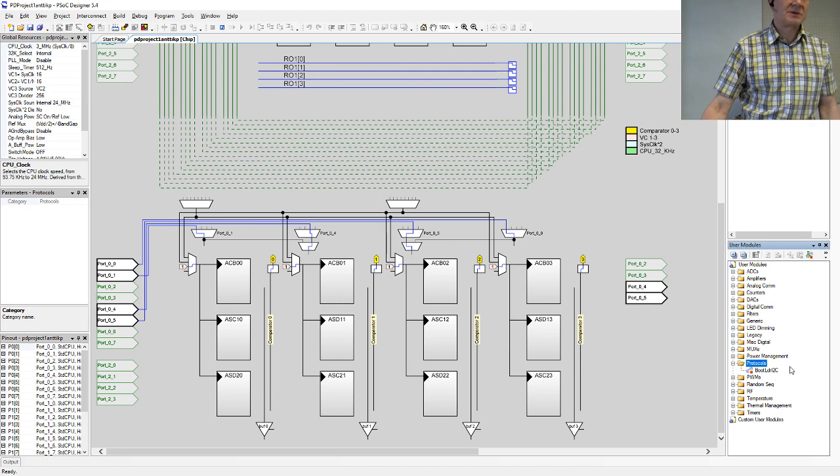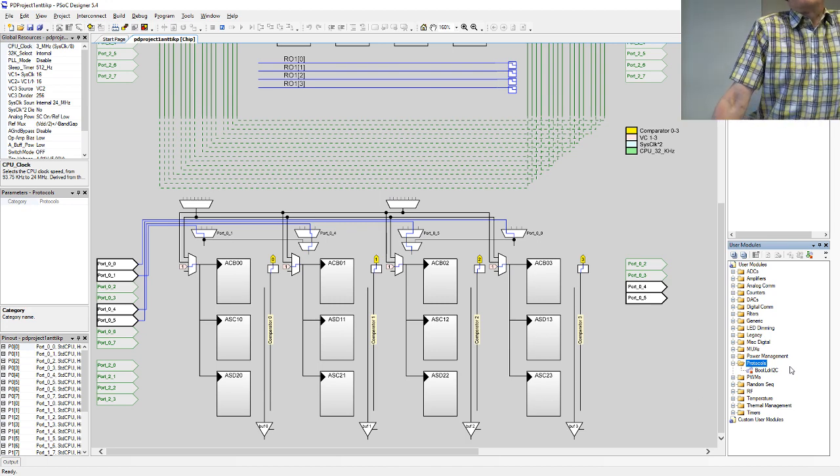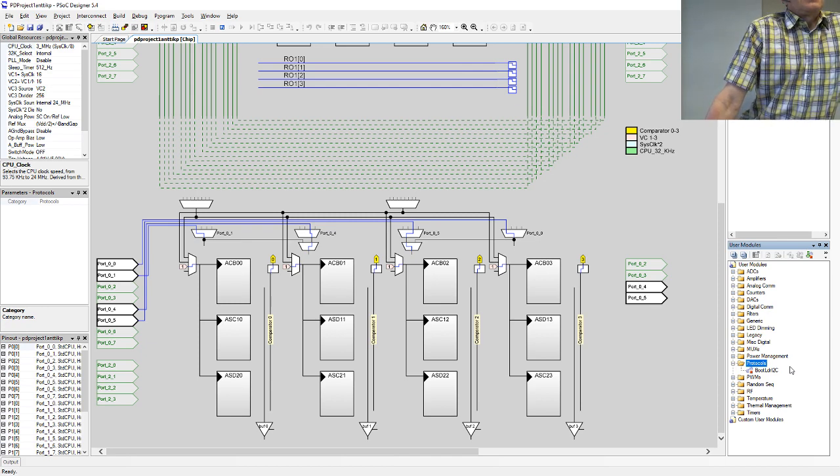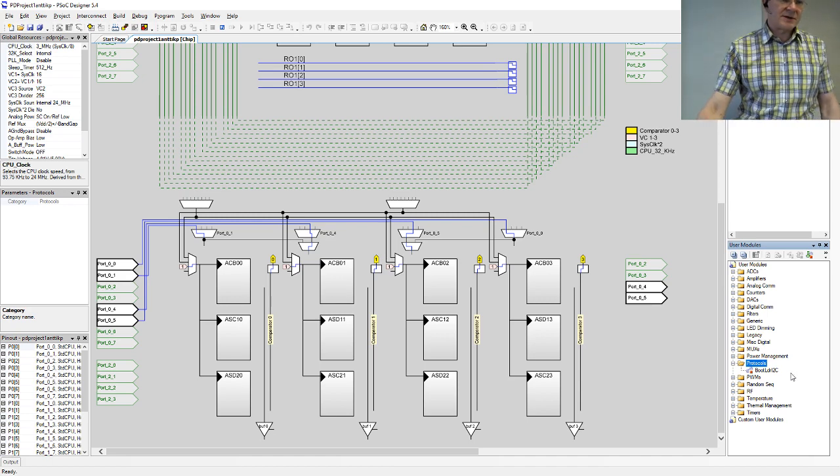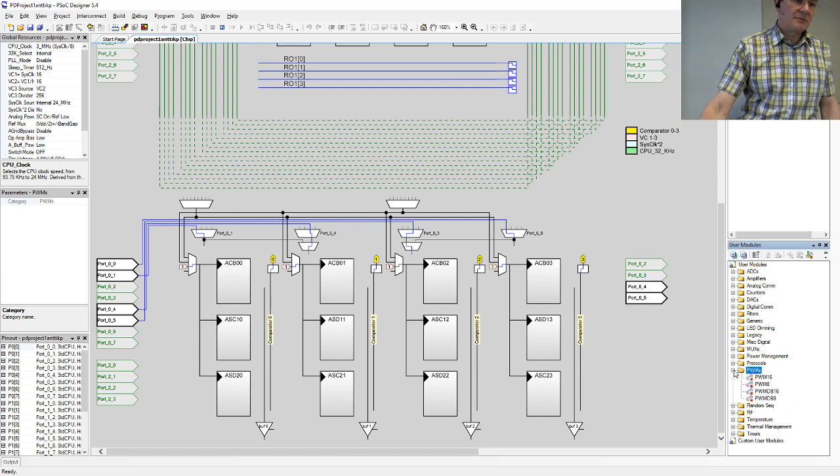Analog multiplexers, good. Some power management protocols. Okay, protocols. Well, you can also have external I2C memory and use that one as the program memory, and have a bootloader that first loads the boot code from the I2C chip and then starts executing it. Well, different pulse width modulations, random sequences.